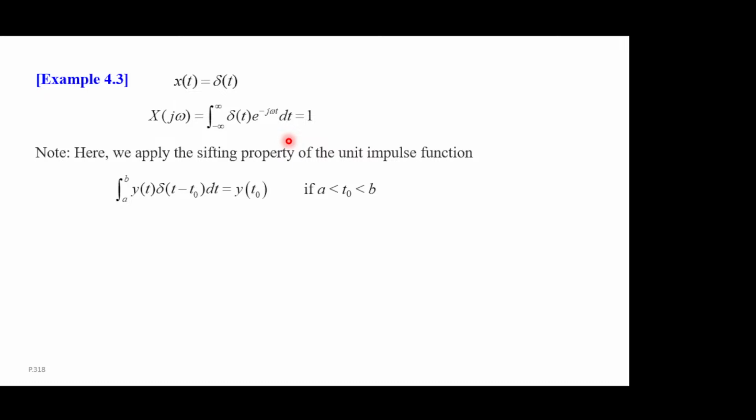Okay. So we found that this very sharp peak, delta of t, if you do the Fourier transform, actually has every frequency with the same amplitude. If you think about the spectrum, it's actually a constant. Something very interesting. So delta of t under the Fourier transform becomes 1 for every omega. Remember, this is a function of omega, but it's just a constant function. It's 1 everywhere. And this is something that you want to remember. We'll see a generalization of this.